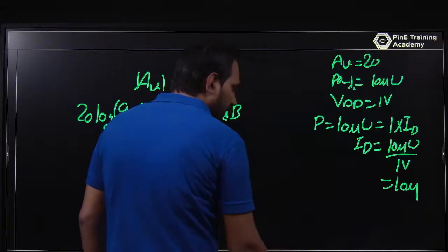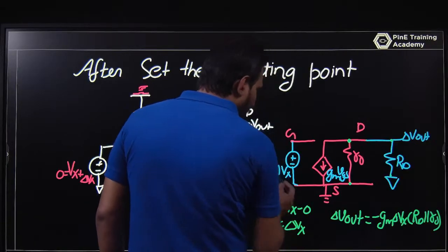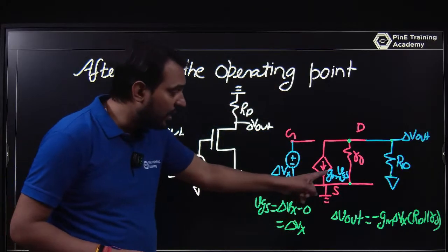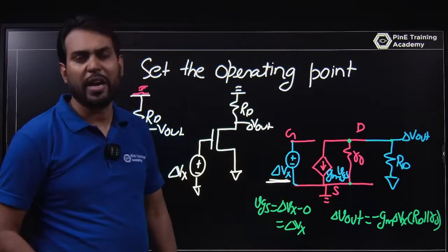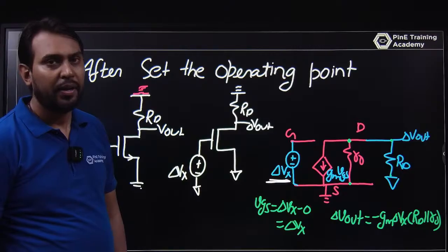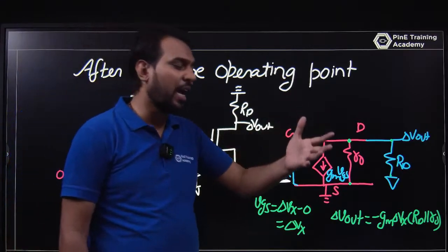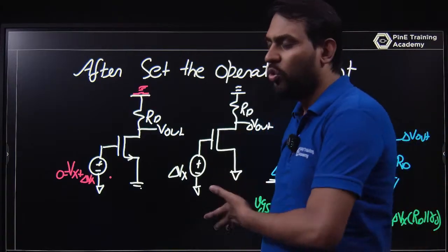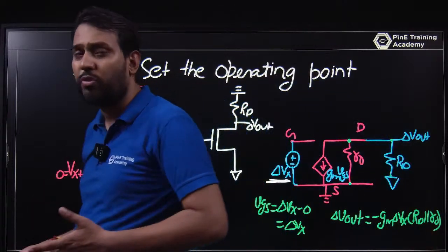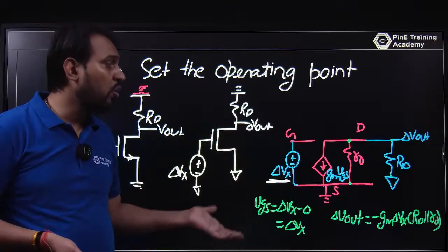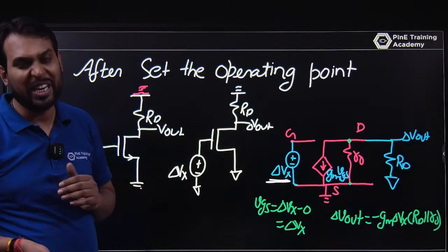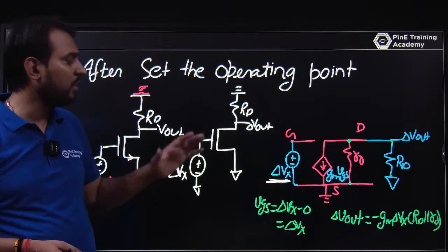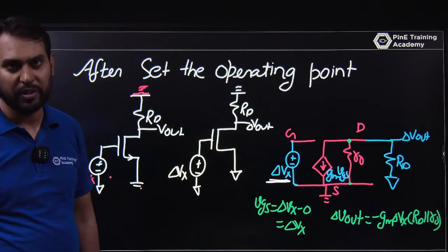Basically, what is happening in a small signal model, you can check it. You are changing the gate voltage and you are finding the drain current, which depends on Gm VGS. This is a voltage controlled current source. You will use the common source amplifier everywhere, in a differential amplifier, current mirror, or OTA, for amplification. This is very good for amplification. It is just like a common emitter in a BJT, which has a 180-degree phase difference. This common source amplifier also behaves with a 180-degree phase difference.